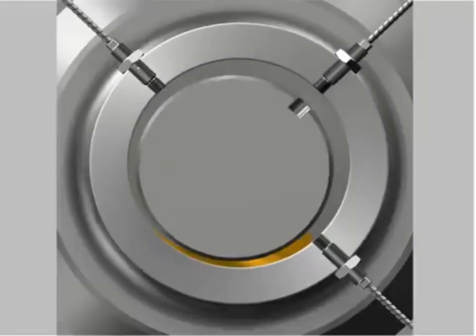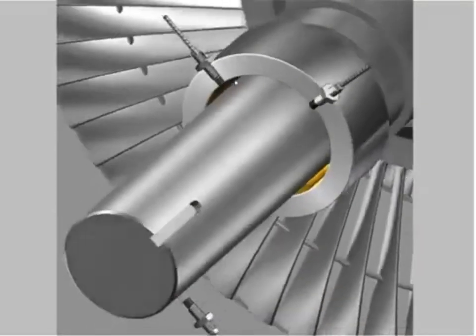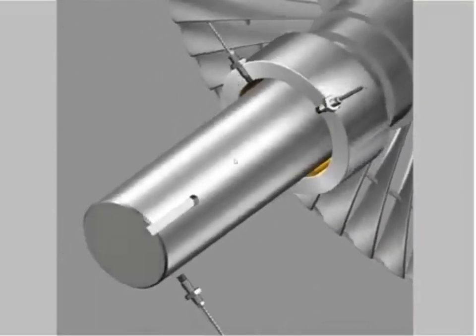So we're actually using two proximity probes, two displacement probes, to tell us about the radial motion, and we use another proximity probe, commonly called a key phaser, which is in a position to pick up a once per revolution event, in this case a keyway.